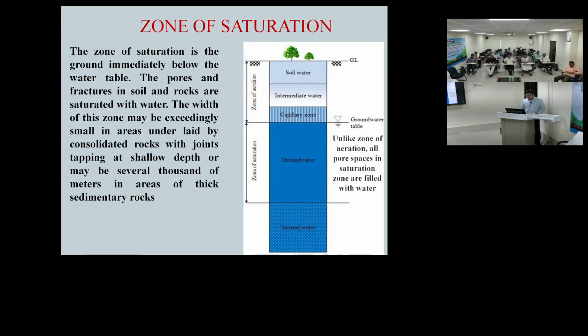When I was in Bihar, we didn't get any clay layer. People from Bihar will know, near the confluence of the Kursela river and the Ganga river, up to 280 meters we only got sand. But in some cases there are intermediate clay layers, because it depends. Here, as I have told, in a valley-field area like Guwahati, near Tetelia Bori, close to our office near Betkuchi, this soil zone or weathered zone is up to 24 meters, whereas at BSNL we got it around 68 meters.